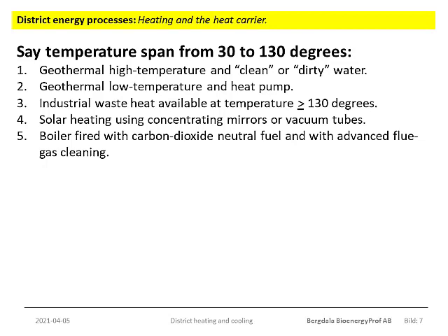The very most extreme case is that you have free access to oxygen-free and non-corrosive water at, say, 130 degrees temperature from a natural source. Examples of that can be found in Iceland. In that case, you may not even have to bother about a return pipe. Or maybe the thermal situation is similar, but the water is corrosive or there is too much oxygen. Then you will have to treat the water first and then just go on. Or you can install a heat exchanger.